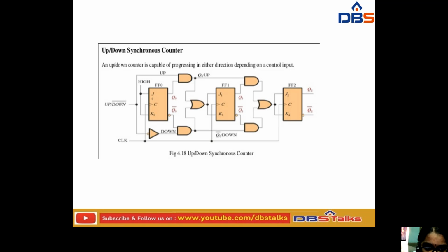So here it is going to take the input. After that, it is going to process the operation. After that, by taking the two AND gates' outputs, it is going to perform the OR operation, and that is given to the next JK flip flop. The output of that OR is also taken as input for two AND gates, and the output of these two AND gates is taken by this OR gate, and again it will be given to flip flop 2, and finally the resultant output is Q2 and Q2 bar. This is about the up down synchronous counter.